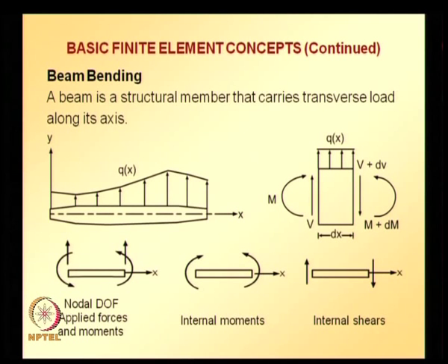However, whatever equations we derive in this course, we will limit ourselves to cross sections which are symmetric with respect to the plane of loading, and the x axis passes through the centroid of the section. As shown there, a typical beam lying along the x axis and loaded in the xy plane is shown.